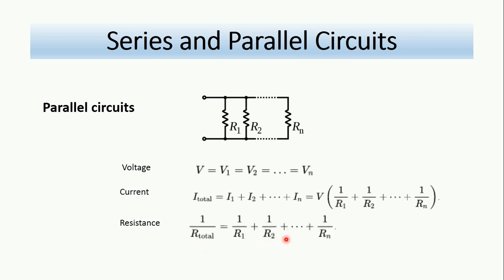Now see that this is exactly how it looks in the capacitors. So the capacitors, if they are connected in series, are added in a way like when the resistors are connected in parallel, and vice versa. Next we go to the inductors, and guess what? The inductors will also be the same as resistors. They always follow the same pattern as the resistors. So if the resistors are added in such a way, then the inductors also are added in such a way.